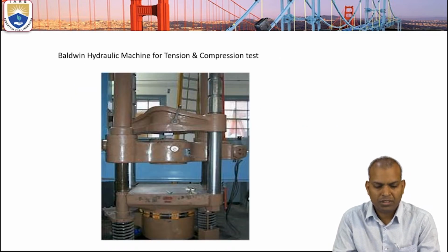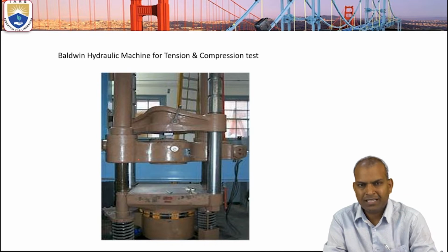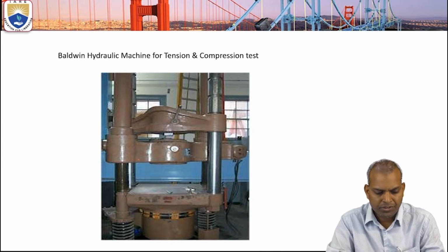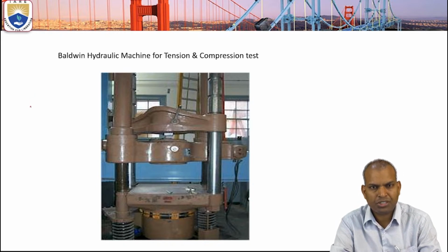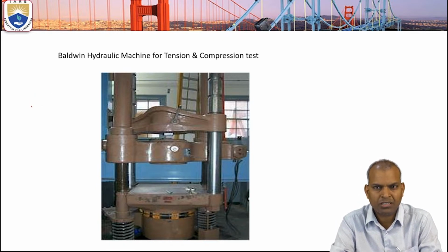Now coming to how to draw the stress-strain diagram. The diagram which indicates the relationship between stress and strain is known as the stress-strain diagram. It is drawn using the Universal Testing Machine (UTM). Under this testing machine, we can test the component under tensile load, and also compressive load and shear loads. There are 3 tests that can be conducted in this universal testing machine.